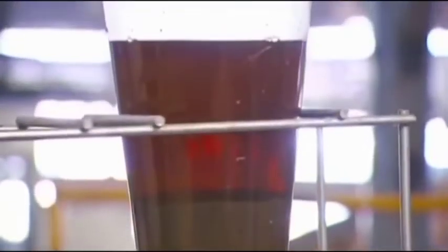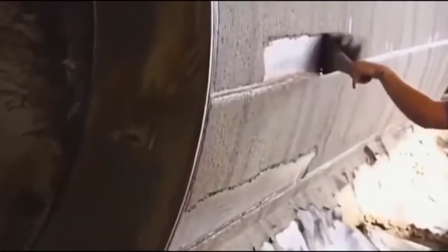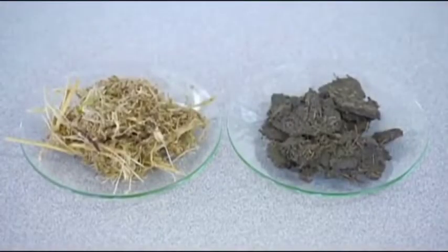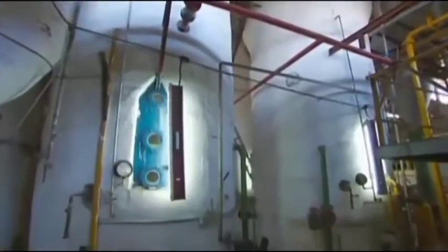In general, the mill uses 3 rollers. The 3-roller mill element consists of one standard support made of cast steel that supports the horizontal rollers: face roller, rear roller, and top roller. Milling rollers. The mill roller consists of a shell made of cast iron mounted on a shaft made of special steel, which is joined by a shrink fit process.